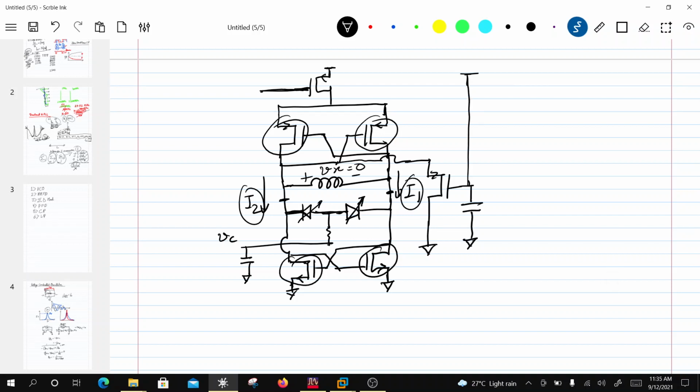So what this does is, when I switch on this circuit, this capacitor stores zero charge, or it's 0 volts here, and then it charges through this voltage. That means that at turn on, this device is totally on, so it's going to pull the current out of here. So I2 becomes much less than I1. This causes the circuit to go out of that stable state, which is undesired. So this startup circuit is going to imbalance the currents I1 and I2 and start up the oscillation. This is called a startup circuit.